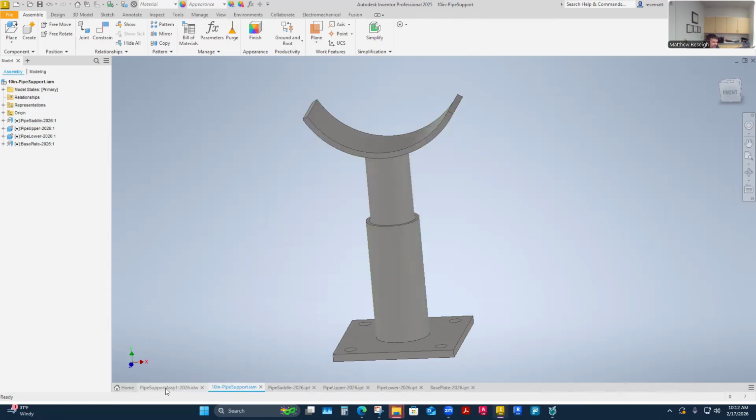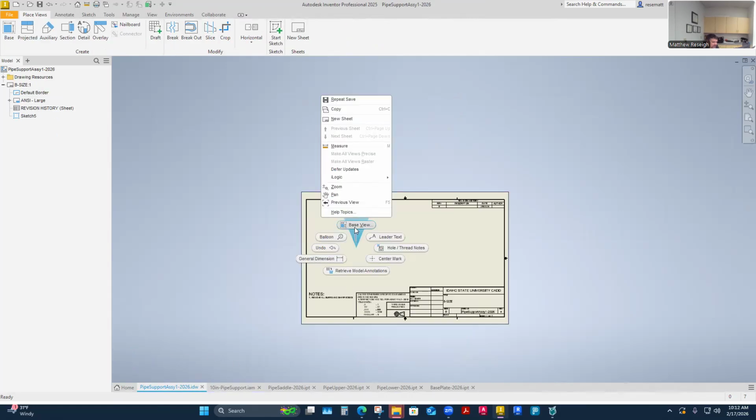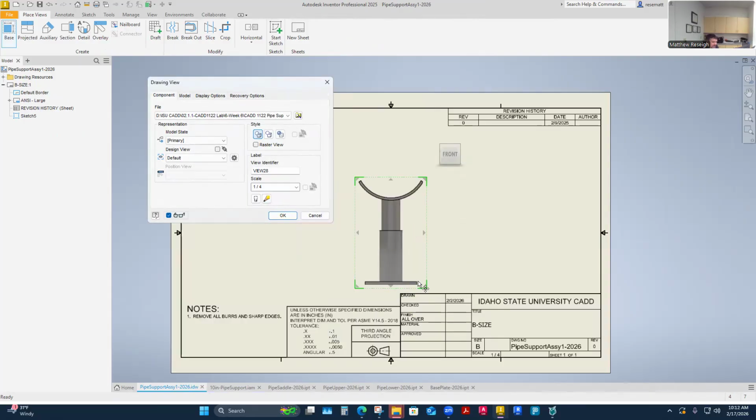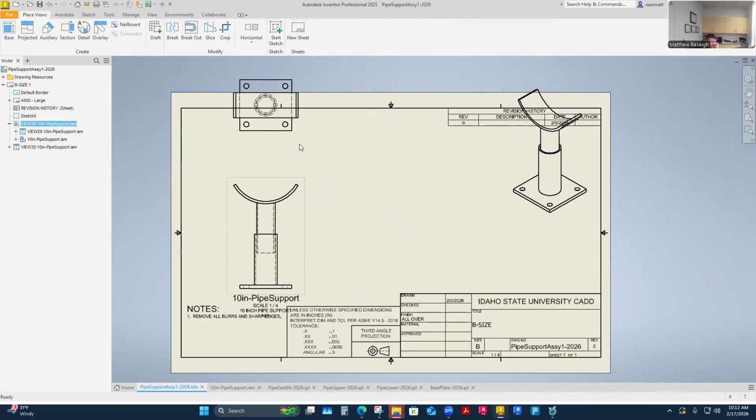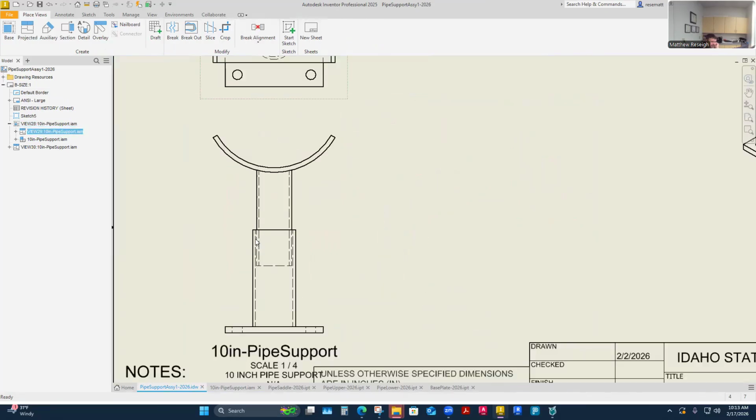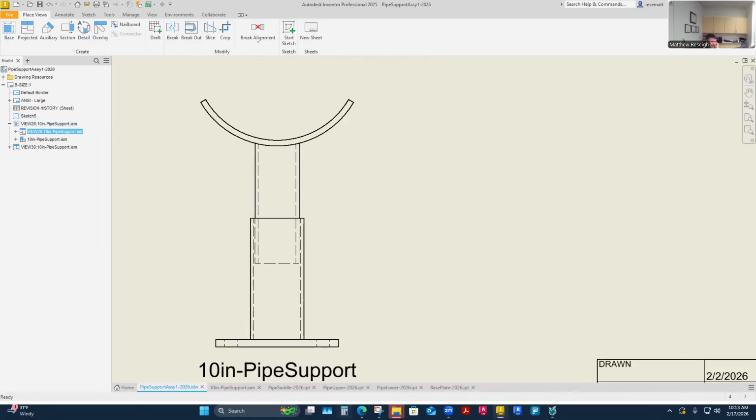And now I'll take a look at that and then I'll put that as my base view. There's the front base view with a view label. I chose to show what he showed because it was enough information to draw. I need a top view and definitely a parts identification isometric view, so I'll drop those two. I think I ended up putting a section view on mine, because I sectioned it so I could see the relationship of these two together specifically, so I could call that out.